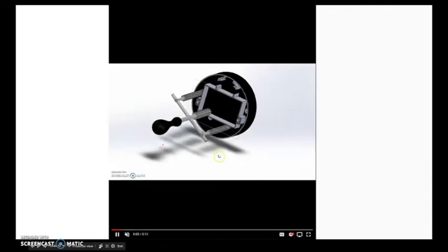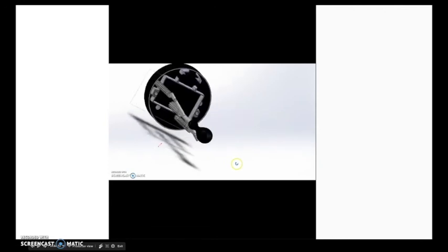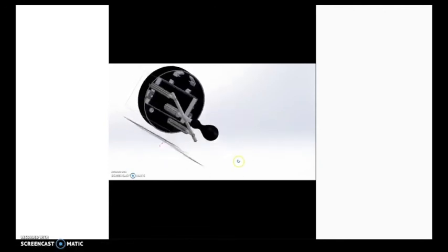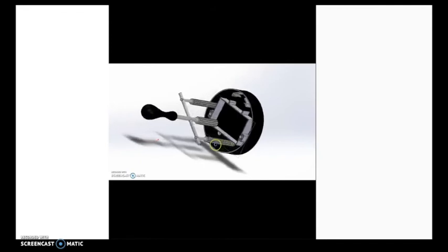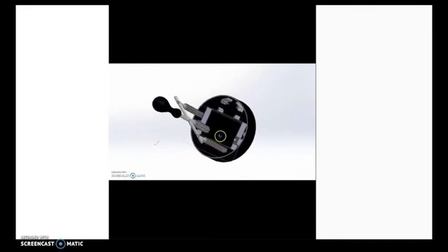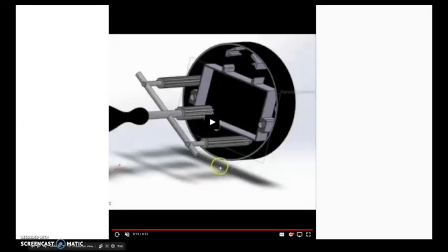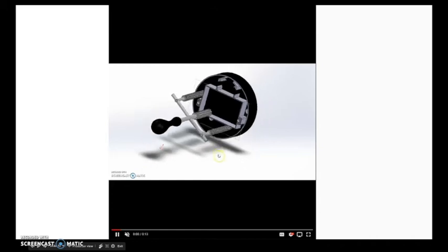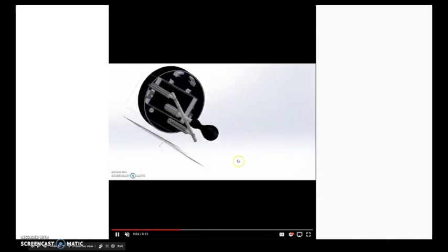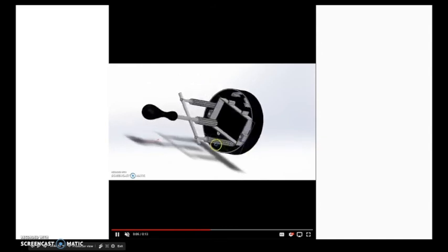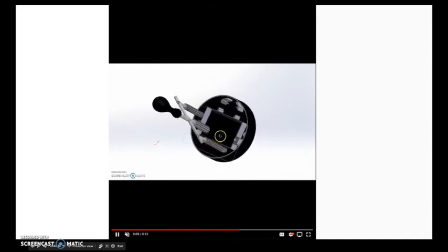So diving into the mechanics behind the tool, essentially the way that it works is that there are 2 belts connected to the inner gear and to the outer gears. What happens is that the employee will turn using the handle, and in return it will then turn the other 2 gears in order to fasten those 2 screws. What this does is cut down the time that it takes to fasten, but keeps the alignment time the same.